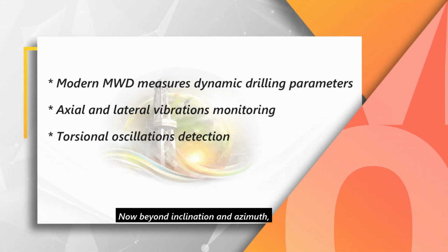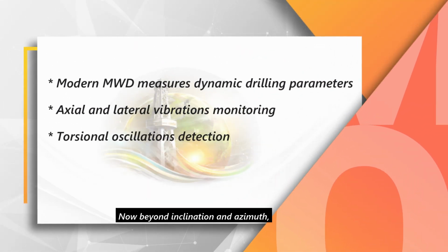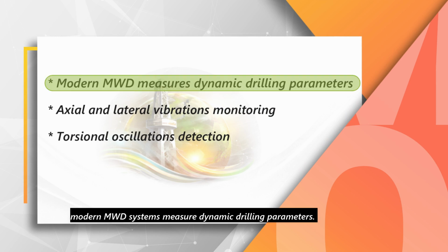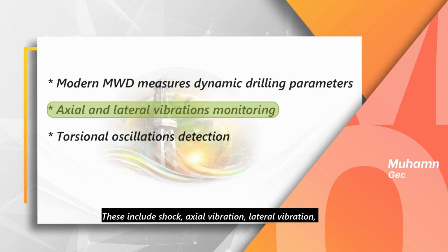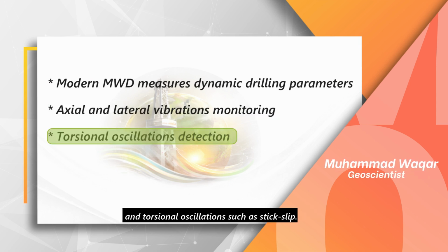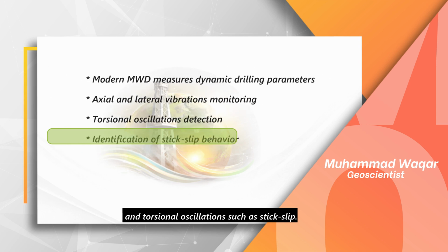Now, beyond inclination and azimuth, modern MWD systems measure dynamic drilling parameters. This includes shock, axial vibration, lateral vibration, and torsional oscillations such as stick slip.